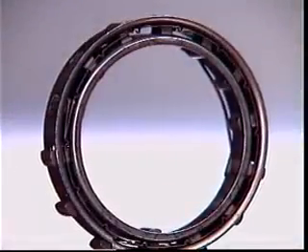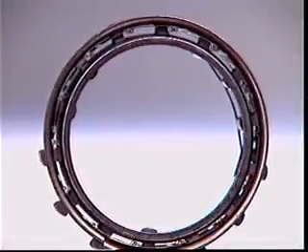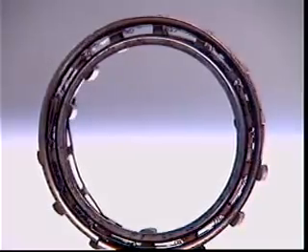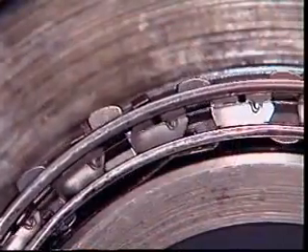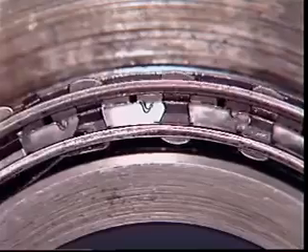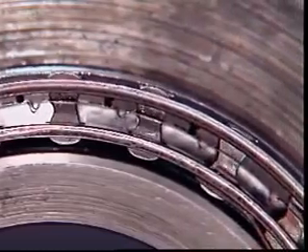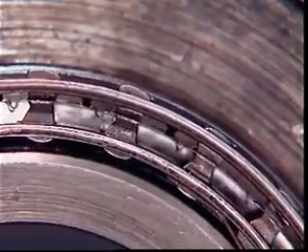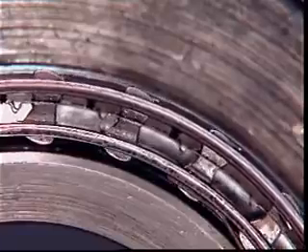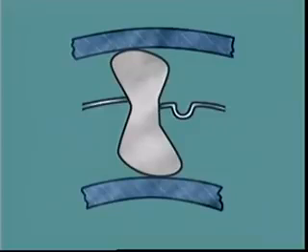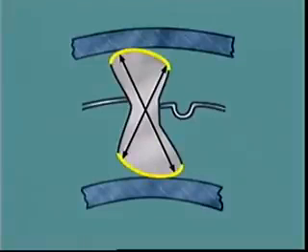The sprags are held in place by a spring-loaded cage. The cage moves the sprags together so that when the stator is locked, each carries an equal share of the load. The one-way action is produced by the different radii of the sprags and the curvature at their outer edges. This gradually increases from the shorter radius to the larger.